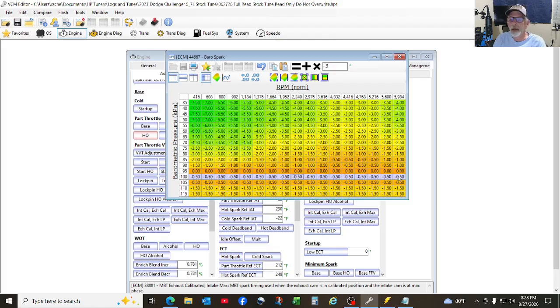But it's a cute little trick. I know a lot of guys come in and zero out this table completely, but you don't really want to do that, unless you're tuning for your barometric pressure average. If that's what you're going to change all your tables to, then take whatever this is and transfer it over, and you do it to the whole table.